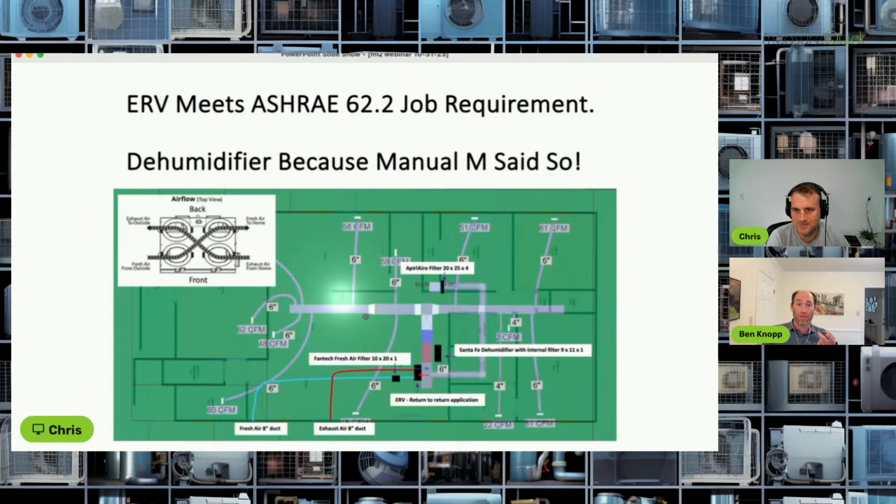So that's why I was really concerned about the 2.5-ton system. Yes, it covers the full heating load. We wouldn't even need electric resistance heat in Blacksburg, and it gets down to 4. I've seen 4 degrees in Blacksburg, and that'd be no problem. We could deliver that with the heat pump and no backup heat. But with that 2.5-ton, yeah, you're right.